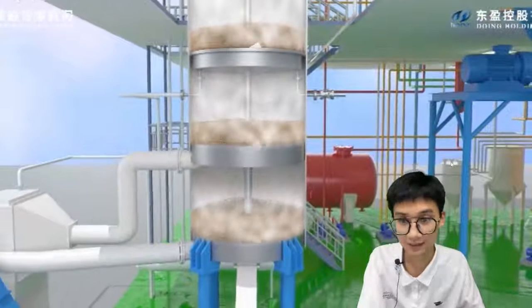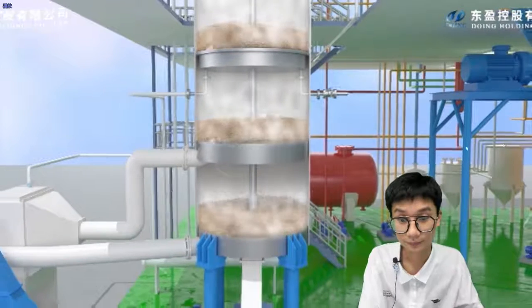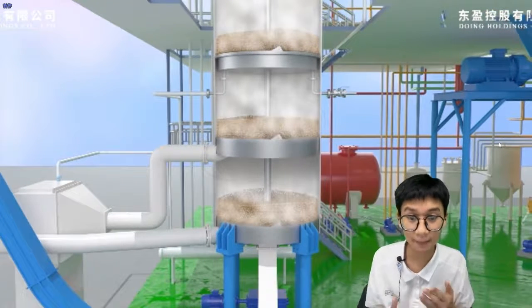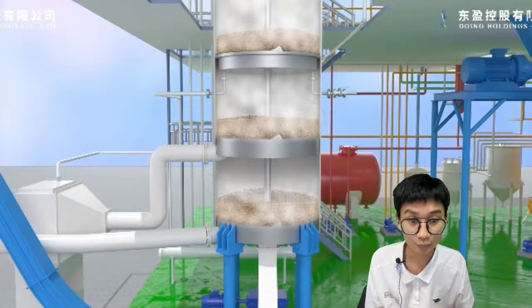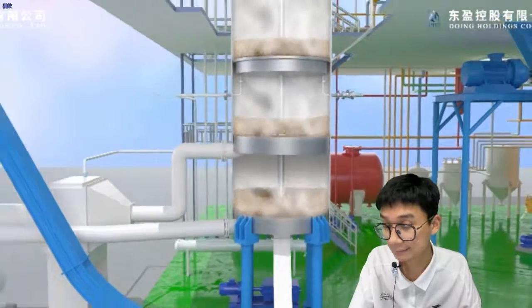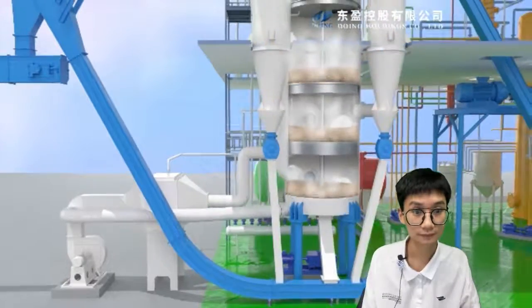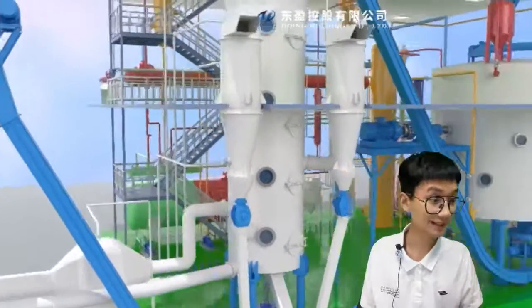As you can see, there are several parts: pre-desolventizing part, desolventizing part, direct vapor layer, and energy saving layer. They have different functions. Each layer is equipped with a pair of stirring fans. In addition to pre-desolventizing through the normal opening door, the other layers use a rotary valve or winch to control discharge and material sealing. This is our DTDC system.